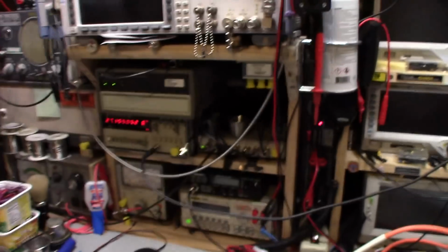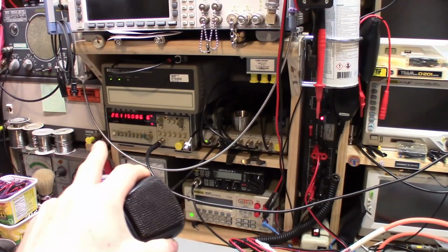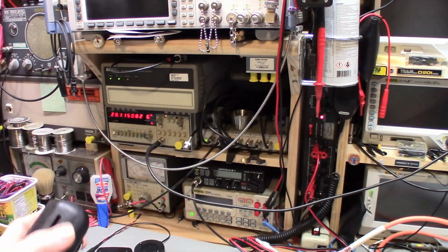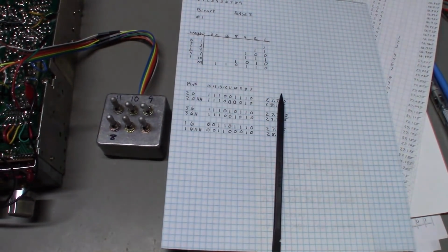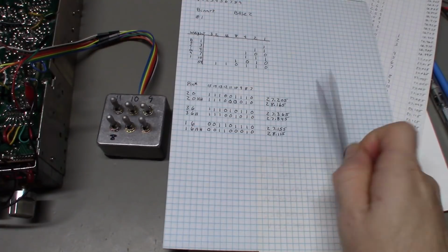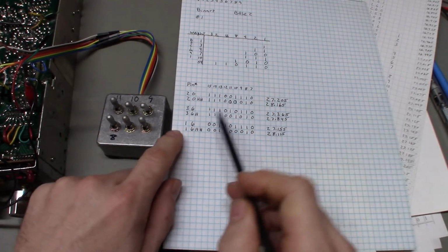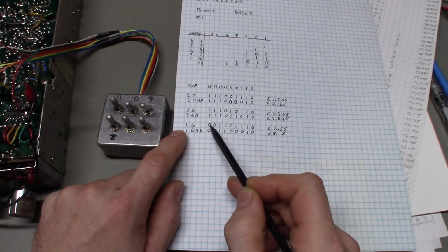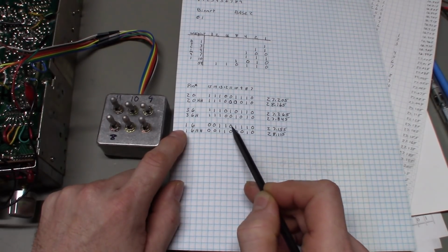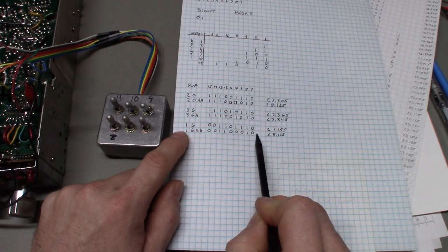So we'll go back up here again, grab the microphone, and 28.115. It's just that simple. That's all there is to it. The old school toggle switch mods, that's all you were doing. You're intercepting what the channel selector is sending out, because remember, I've got the channel selector on channel 16. So the channel selector has a ground to ground, voltage, voltage, ground, voltage, voltage, voltage, ground. And this is what we want.